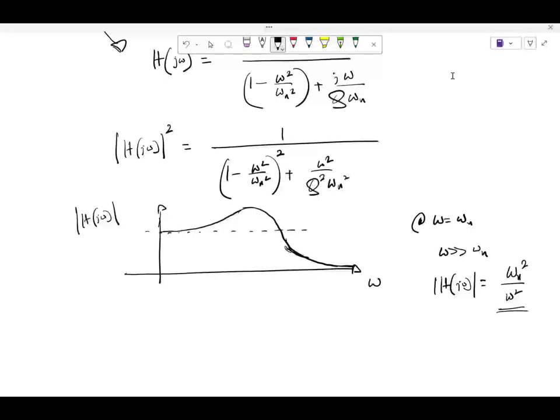And this ratio is what? In other words, what will be this value? Q, assuming that this is 1. If that is not 1, then it will scale. So the amount of peaking you can have in a second order transfer function gives you the Q of the network, if we go by the definition of Q in the second order transfer function.